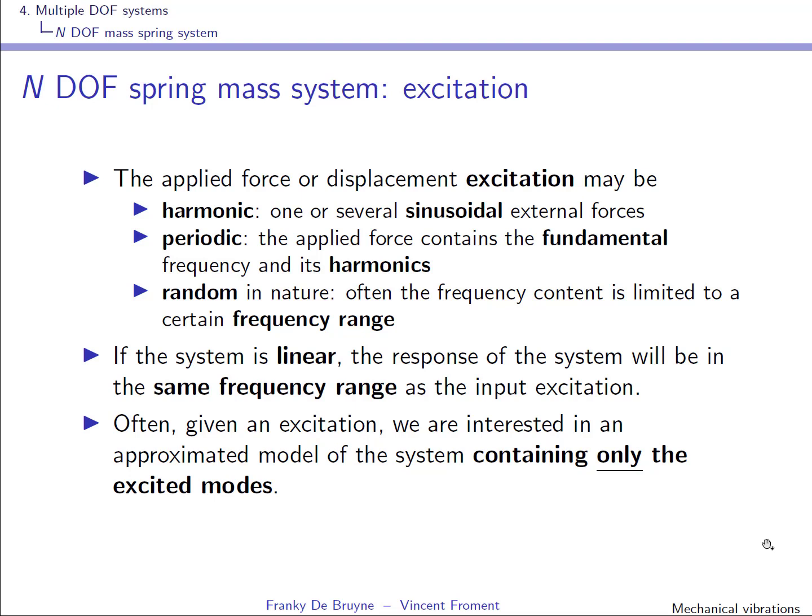Remember also that if the system is linear, the response of the system will be in the same frequency range as the input excitation. So very often we have a complex system, but we know that our input contains only a few frequencies. So sometimes we are interested in an approximated model which only contains the excited modes.